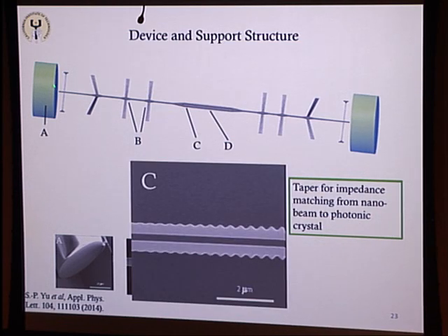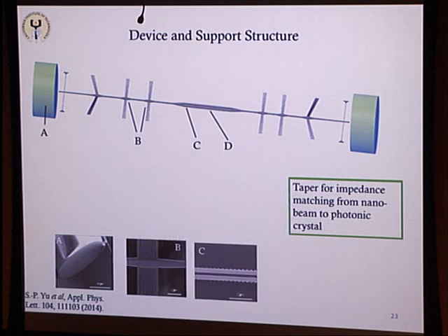To move from this 1D waveguide into this photonic crystal region, we utilize this kind of mode matching or tapering of this dielectric modulation, and that allows us to effectively mode match, or impedance match, from this 1D waveguide into these two beams, because it's actually a pretty drastic change, and so we really want to try and minimize the amount of loss in that system.